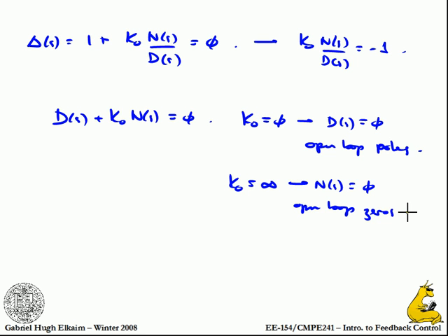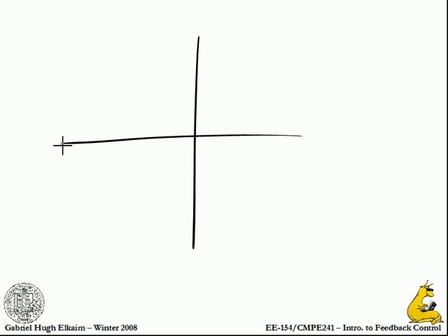Now, what about the zeros that you don't see? This all works fine if I say, hey, I've got a pole here, a zero here, a zero here. Then the root locus of this is going to be that these two shoot towards each other, they break off, and wind up, the two branches end at the zeros.